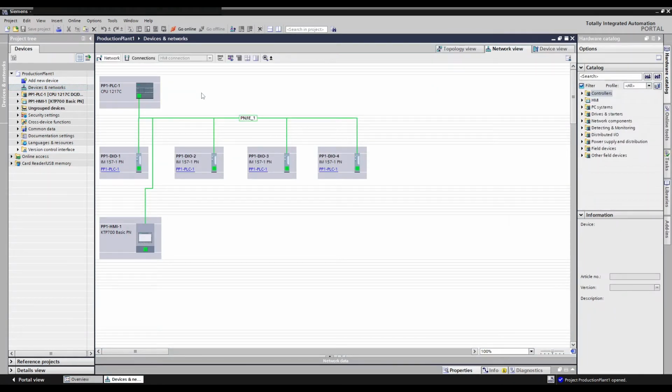And as we can see, I have a 1200 series PLC, a 1217C to be more precise. And I chose this PLC because I have only the basic license here on my whole computer. And this also means that the 1500 series PLCs are simply not available to me, so I had to stick with these. Also, I was actually quite curious if this kind of PLC can handle a large plant like that, so I stuck with it.